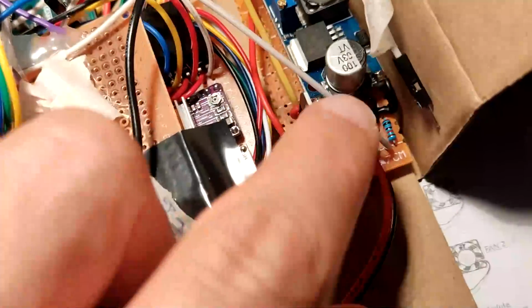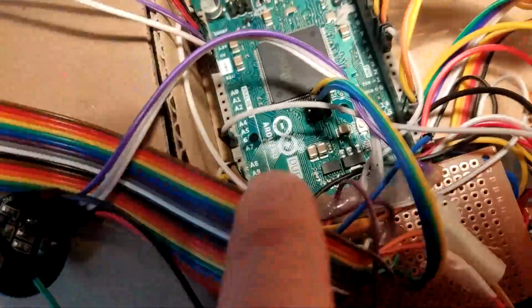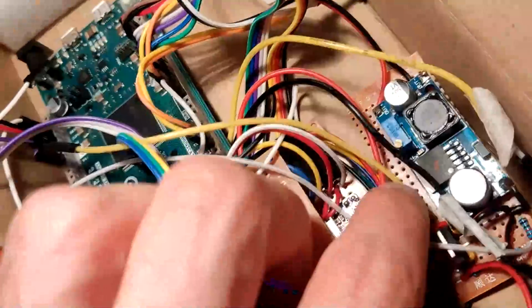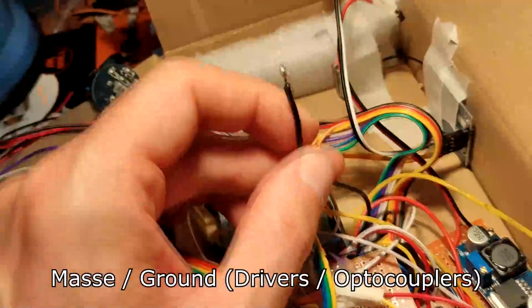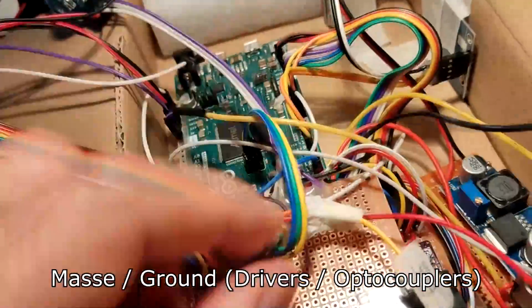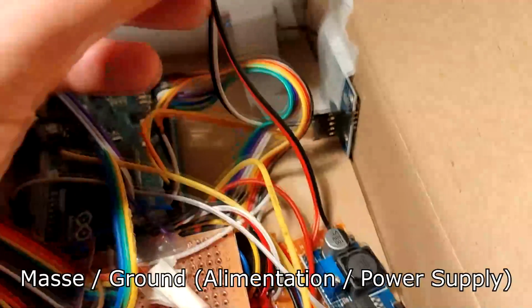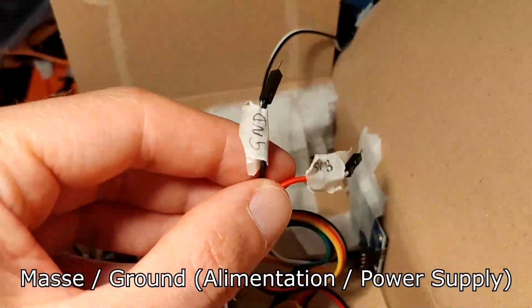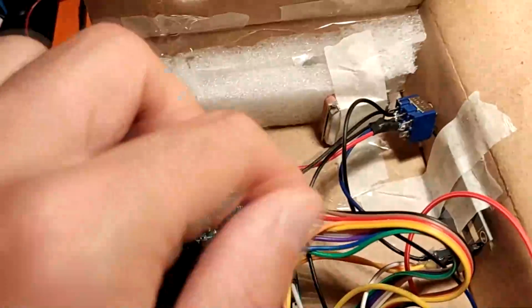And here the white wire is the wire for the battery monitoring, connected to the D7 pin of the Arduino. The yellow V main goes to the V in. This is the ground of the optocoupler circuit, which is soldered on the ground path, for example here. Here the soldering is done. Here we have the 5 volts and the ground coming from the buck. I solder the ground here.